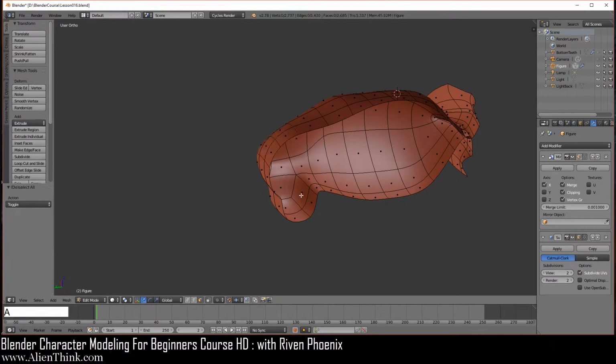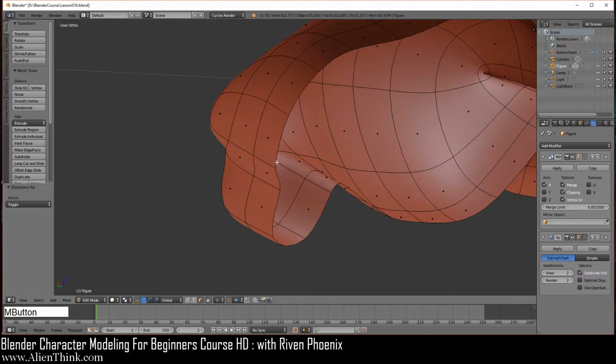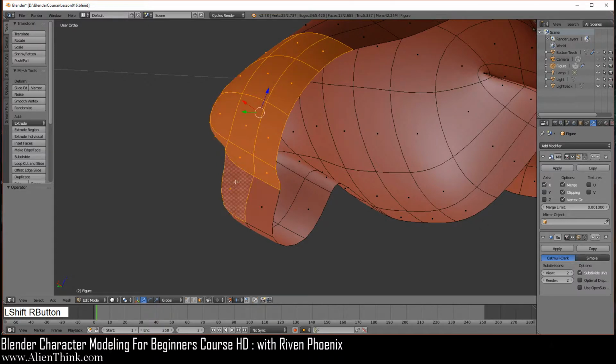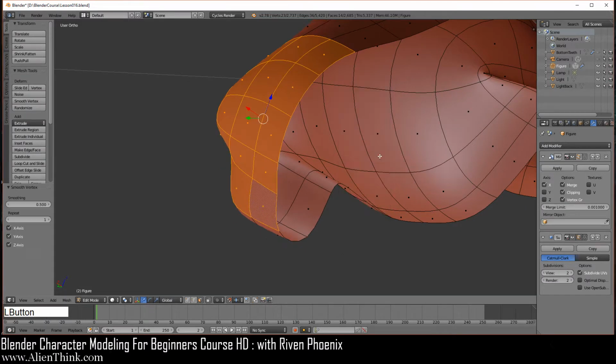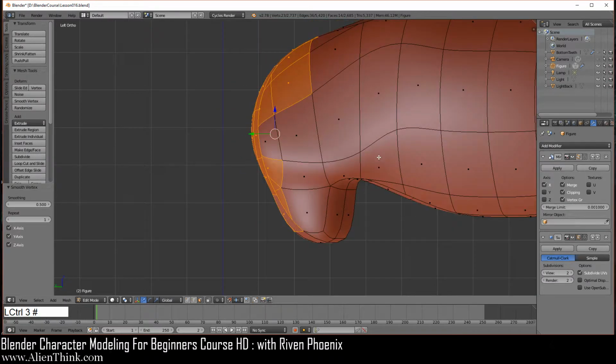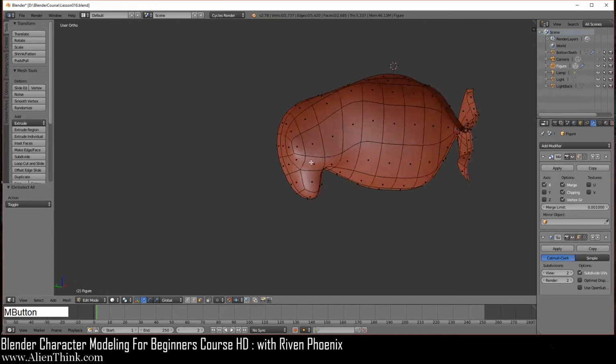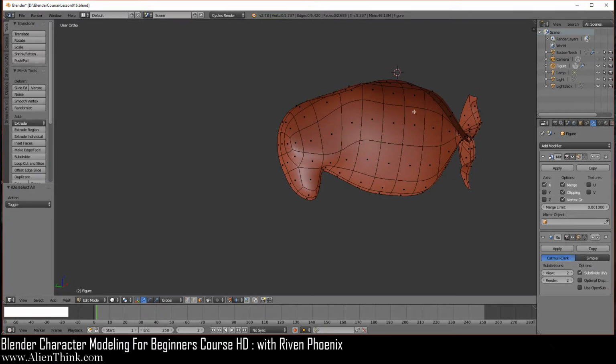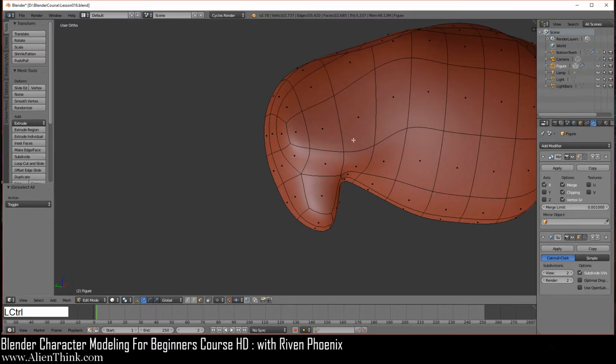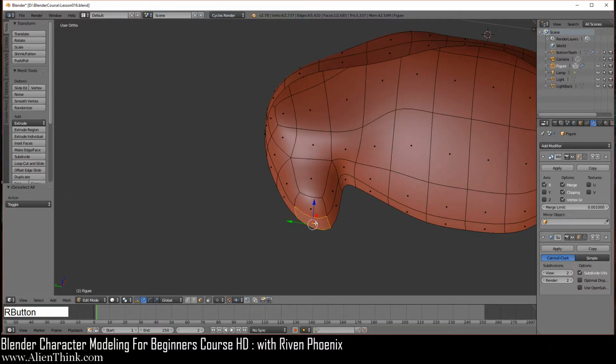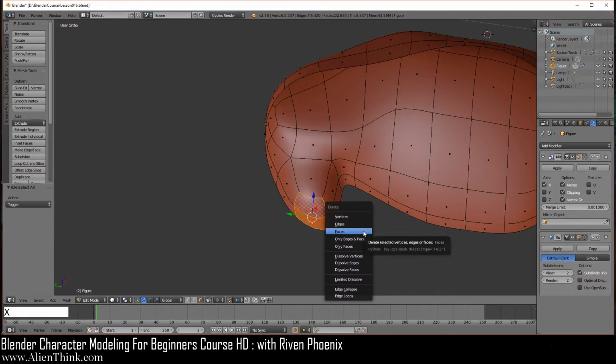Okay, Alt D to deselect. And then you can of course just select, actually let me do Control Z to bring the selection back. Press the shift key down, click on all these guys over here, just do W smooth 1, 2, Control 3. Alt D to deselect. So you can see that what we're getting is this idea for the inside of the mouth. Move here. So Control 3, and of course just click on these two, X, and delete the faces so it gets an opening.